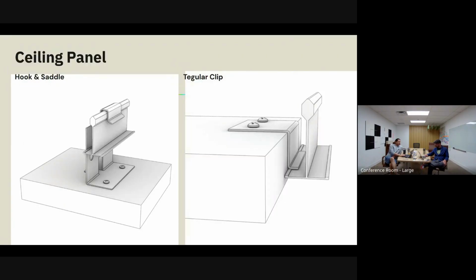Okay. All right, ceiling panels. This is specifically about T-grid, right? There are 3 types of panels that we make that can go with T-grid for the wood acoustics. One of them is a lay-in tile. With lay-in tile, there's no hardware. It's like any other ACT grid, any other panel that you see. You just pop it up there and lay it in, right? It literally rests on the lip.